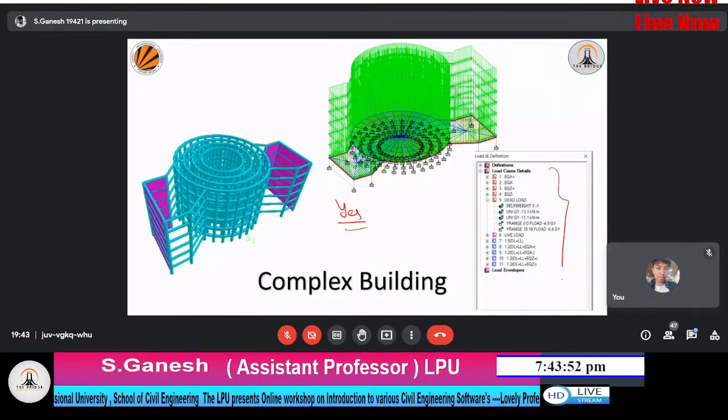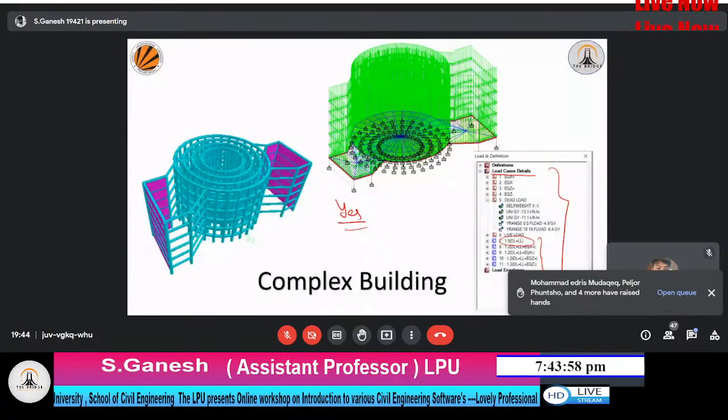So you can see the set of load inputs, how many load cases are added, and the combinations in depth. If you see the combinations, we have some seismic inputs, and how the seismic inputs are running in the building, right? This way we can make the models.